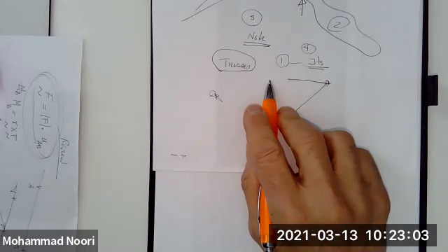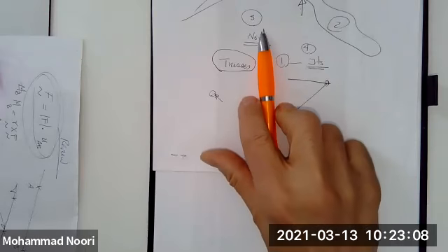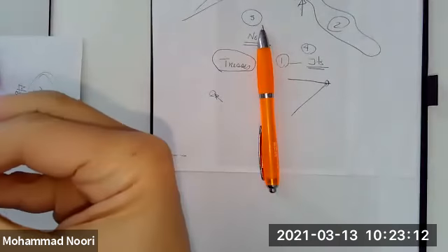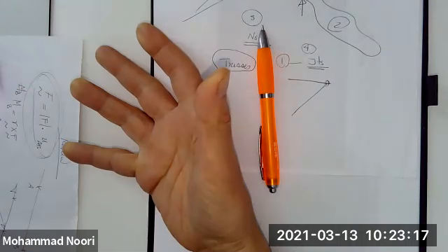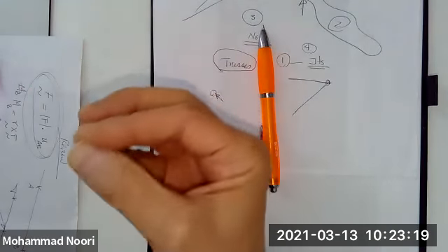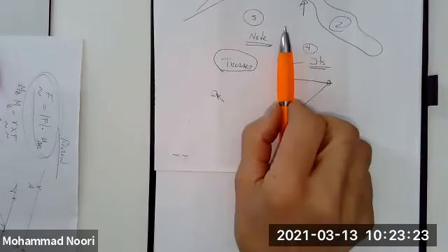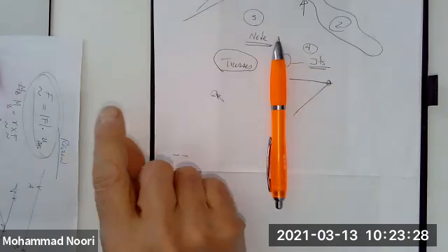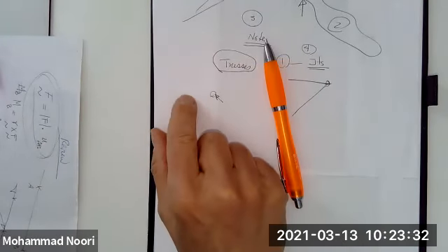Since you have three unknowns, remember all these basic important concepts we learned, because those were meant to save you time. Summation of moments was meant to save you time. If you have three unknowns in a truss that you've cut, and you only want to find one of those members, I guarantee the other two members intersect at a point.